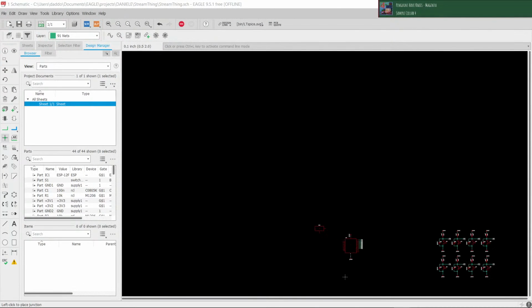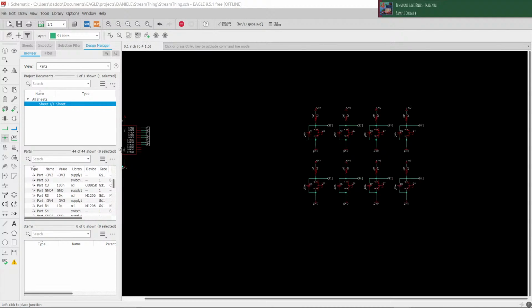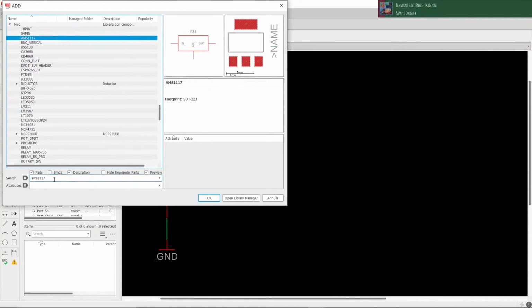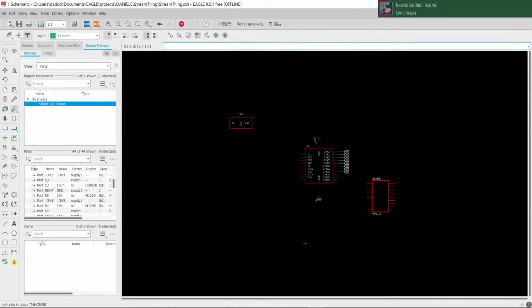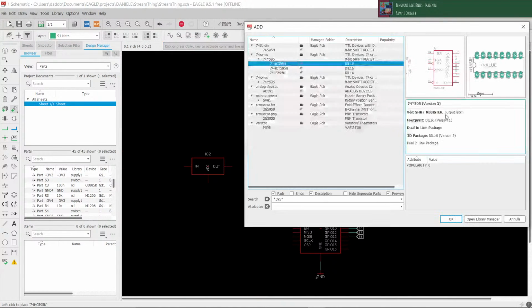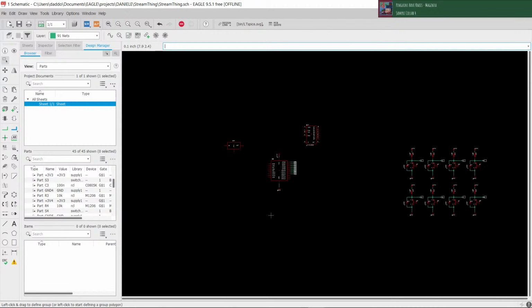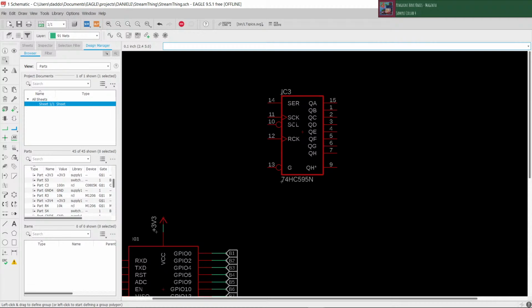But also, what I wanted to say is that I want an LED that shows what scene I'm in, and since I ran out of general purpose input outputs, I can use a shift register, like a 595. I will be using the through hole one because I want a low profile board, so mainly SMD components, but since I want it to be as cheap as possible, I want to use stuff that I already have. So serial clock, serial clear. Okay, G is output enable, so it should be to ground.